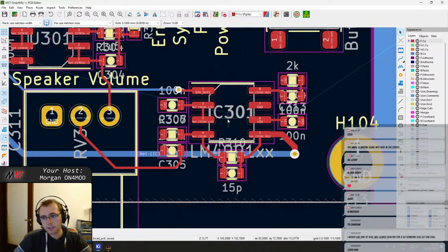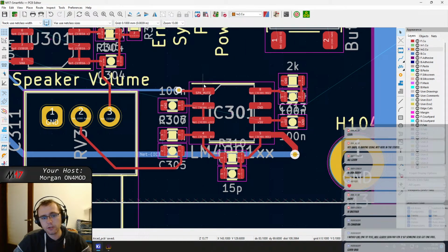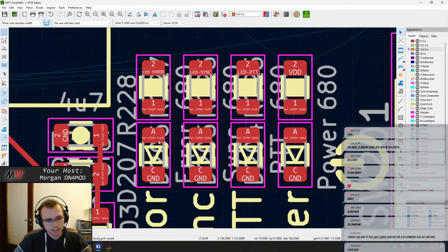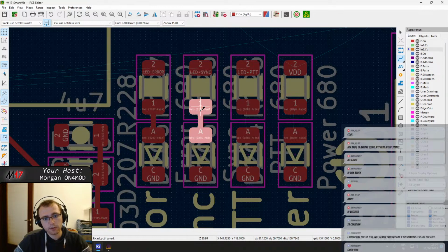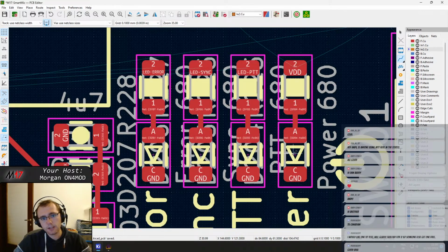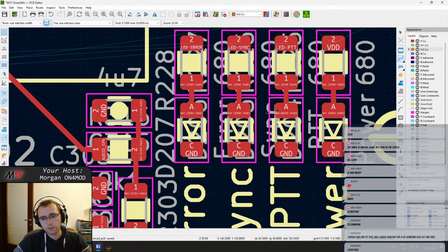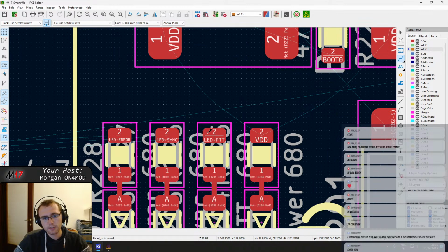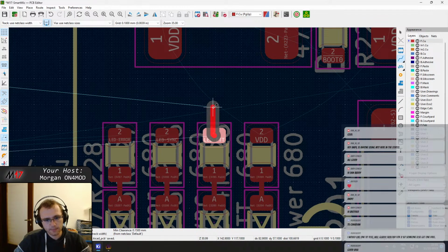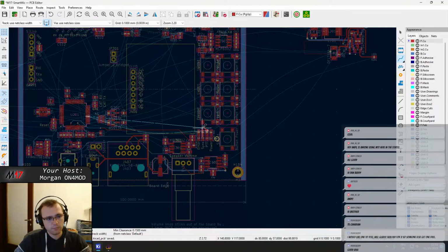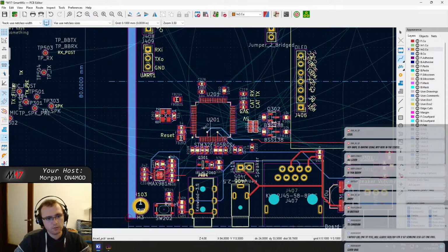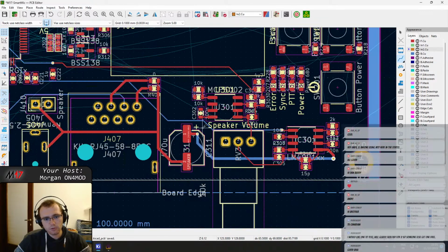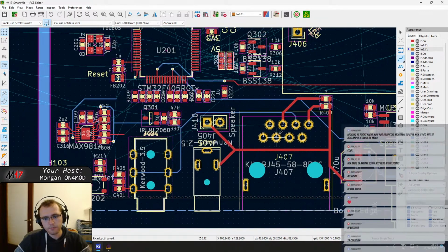So the plus 5 volt is gonna come from the third layer, which is gonna be dedicated to power supply. So I'm gonna write that later on. Those, it's easy to do. Let's do it like this. This is ground, so it's gonna stay right like this. VDD, great. LED signals, I'm gonna go to the MCU. So basically we don't have many more signals to route around here.